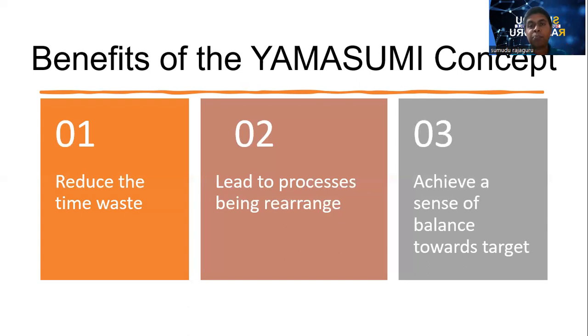First, we have to do an element-wise time study. So we have to divide the elements. By dividing the elements, we can identify what is value adding and non-value adding. So first, we have to attack the non-value adding activities. After that, to attack the value adding activities, we have to do method study and workplace arrangement.